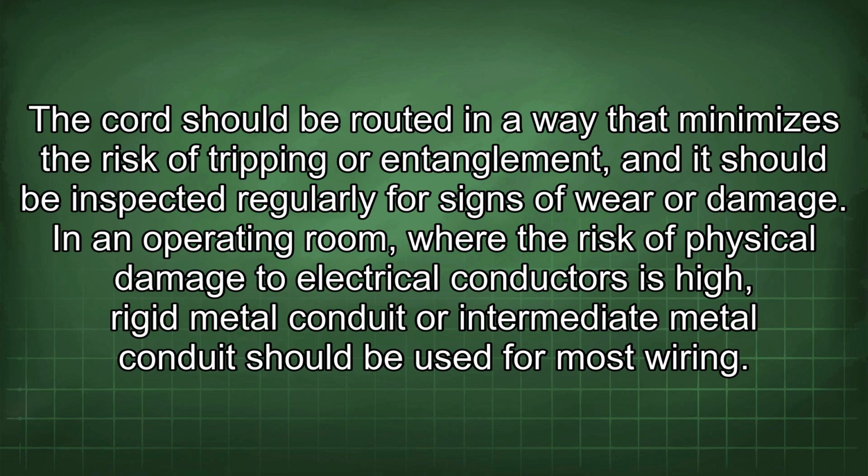In an operating room, where the risk of physical damage to electrical conductors is high, rigid metal conduit or intermediate metal conduit should be used for most wiring.